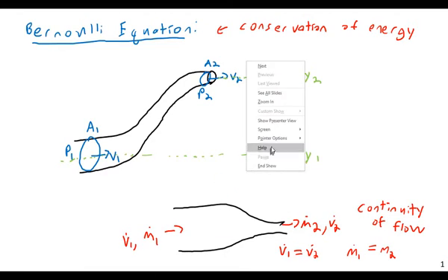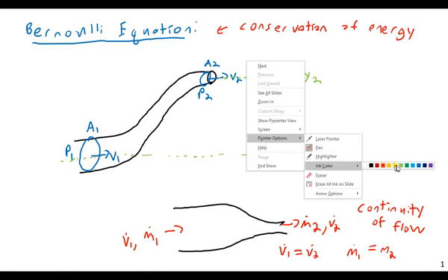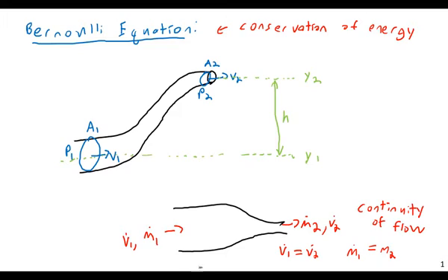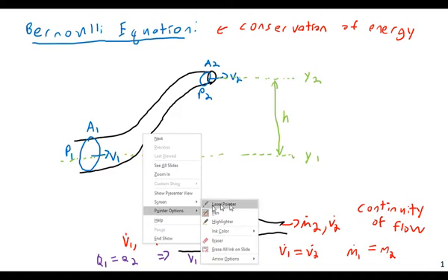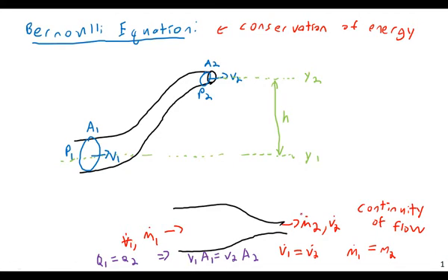And so we have a relationship that we can use at points through the day today. If V dot 1 equals V dot 2, or more commonly referred to as Q1 equals Q2, where Q is your volumetric flow rate, then V1 times A1 equals V2 times A2, where the V1 and V2 here are velocities, not volumes. And actually, if I was going to be consistent with what I've used previously in the semester, if I'm going to use a V for volume, I might just use a barred V here.